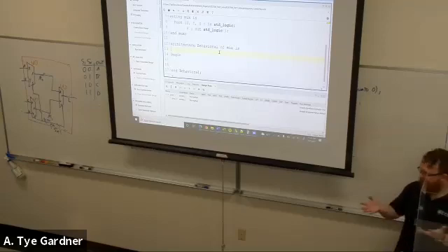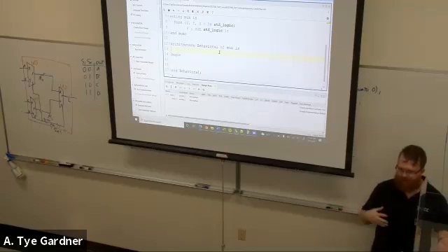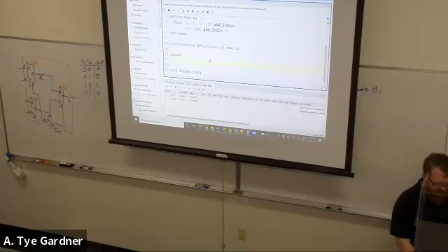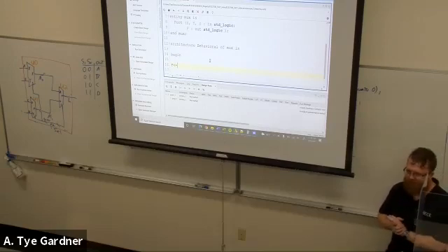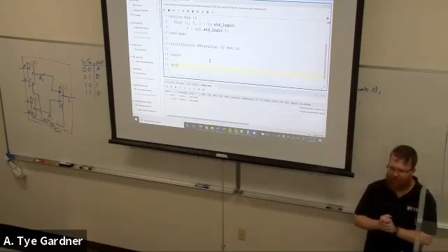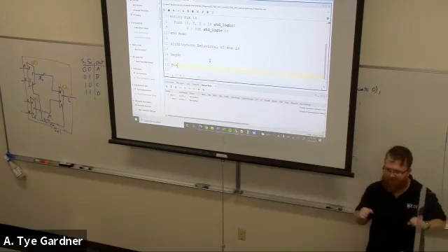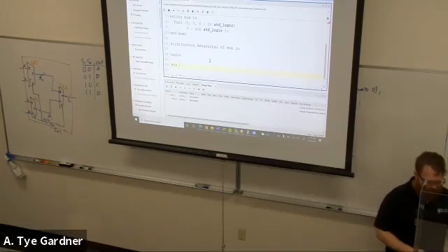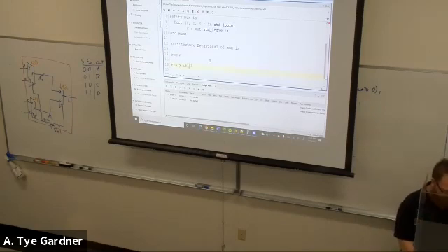I don't need to declare any signals because all of the signals that I'm going to use are my ports. So then my begin. Remember I said I need to assign my outputs, any and all outputs I want to assign a value for, because if I don't assign a value, they're, I don't know, and that can cause problems. And then I need to say, what is F? Well, it is X when S equals 0, else Y.